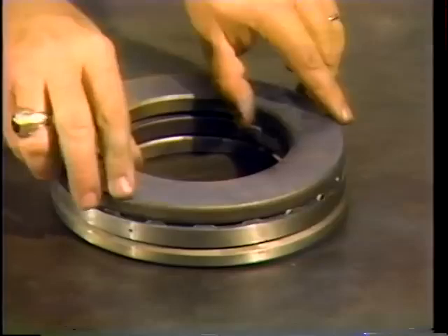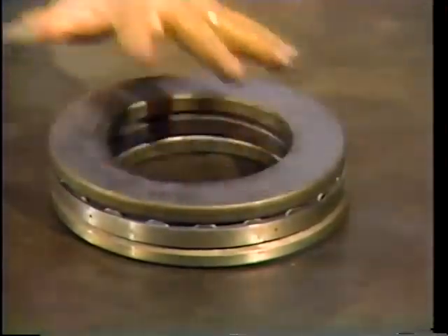Rolling contact bearings experience rolling friction that is considerably less severe than sliding friction. Still, they must be properly lubricated to reduce heat and wear. The useful life of a rolling contact or anti-friction bearing would be drastically shortened if the bearing were operated dry.